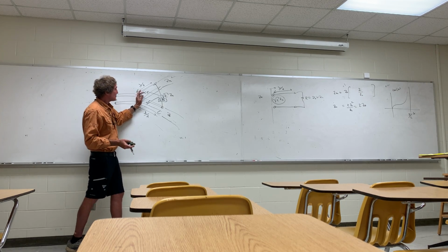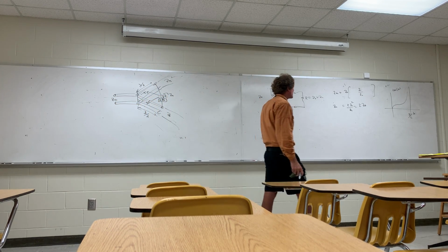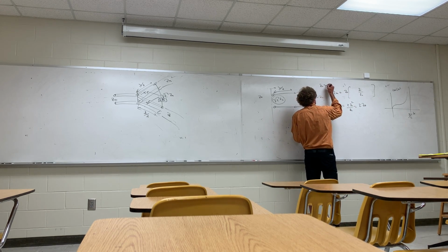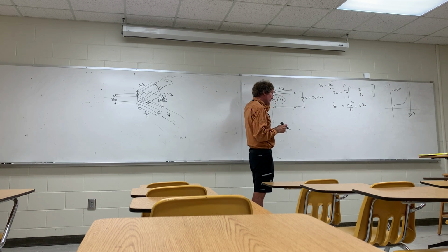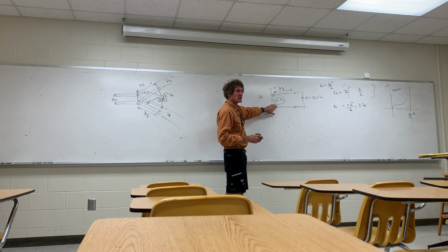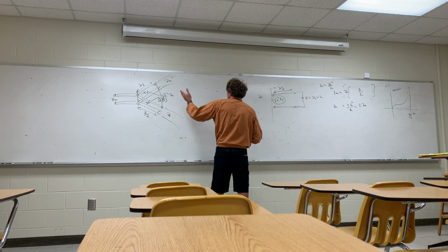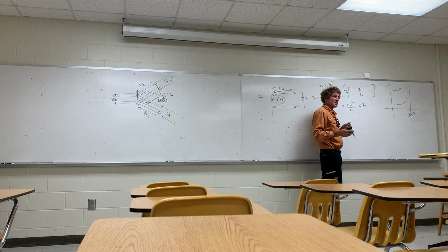So it gets that. Now the reason. Sorry, I think I lost you. So Zn here would be equal to Z naught squared over ZL, right? That's after I got rid of the tan function. So then, how'd you substitute Z naught in for ZL? All right, what is the actual characteristic impedance of the transmission line here? It's square root of 2 times Z naught. Square that. You get 2 times Z naught squared. And what is ZL? Well, the load is Z naught, right? So then I get 2 Z naught squared over Z naught, which is just 2 Z naught.